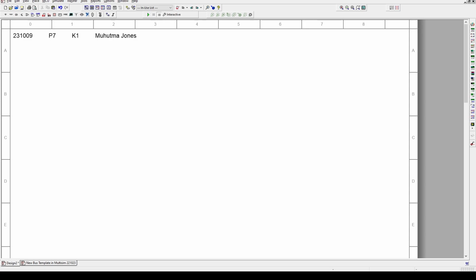They are the 00, the NAND gate, the 02, the NOR gate, the 04, the NOT gate or the inverter, the 08, the AND gate, the 32, the OR gate, the 86, the XOR gate, and then the 266, which is the XNOR gate. And I also told them about the buffer, but that wasn't actually listed in the group. I do talk about it, though.